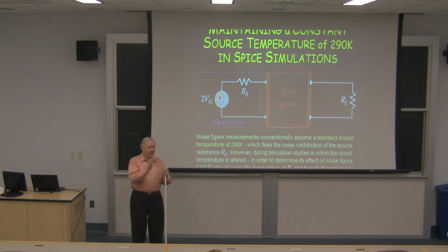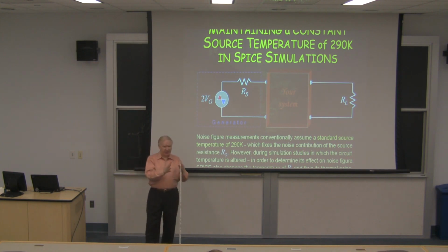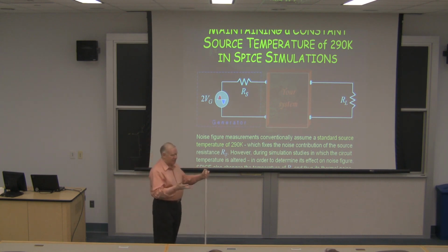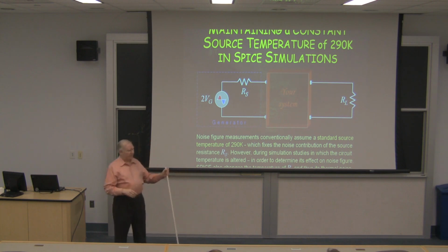The concern here is that the presumption is that the source is at a constant temperature. And it gets quite interesting to ask, what is the noise of an antenna? And in the end, it comes down to the fact the antenna is coupled into free space with impedance 300 ohms. So that 300 ohms can be regarded as dissipated, believe it or not. And it acts just like a resistor, eventually after being maybe transformed down to a different impedance. And it's the impedance RS.